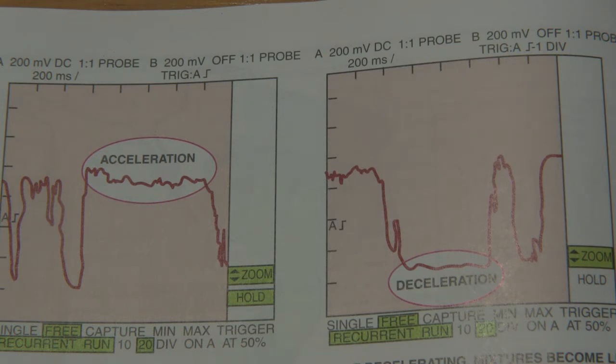And so typically you'll see a naturally aspirated engine will be happiest around 12 to 1 air-fuel ratio. So remember, stoichiometric, 14.7, 12 to 1. We're not dropping a whole lot. Boosted engines, your turbochargers, your superchargers, they like to run closer to 10 to 1. Now, there's variances there, compression ratio of the engine, a whole bunch of other factors that come into play, but